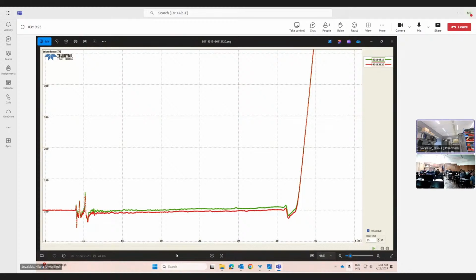Okay, so what we can see here, actually, I don't know what happened with the application, but it crashed. And yeah, we see that when we launch the test signal, we encounter 100 ohms. And these 100 ohms are actually from the cables. You saw these coaxial cables. They go differentially in 100 ohms. Then we encounter a discontinuity. We see that this discontinuity introduces this profile of the impedance. This is 100 ohms. And then you see that we are entering the cable here.